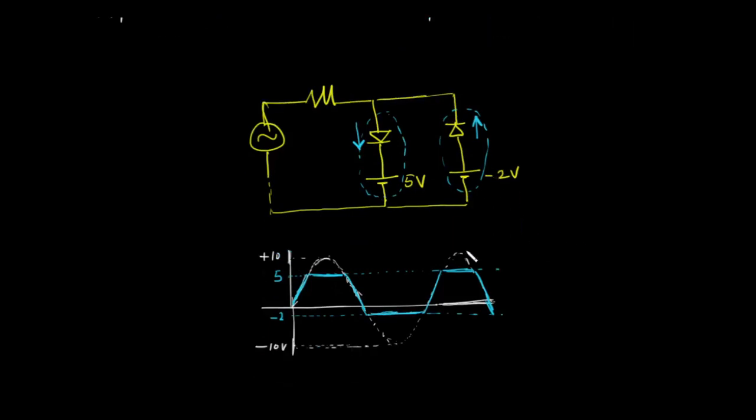In your exam you will be asked to, suppose, design a circuit. When we tell you to design a circuit, what you will have to do is basically draw the directions of the diodes properly, whether it will be a positive clipper or a negative clipper, and give the value of the voltage sources carefully. Suppose I give you a signal like this, and ask you to draw a circuit that will not allow anything above 3 volt to pass. So how will you draw that circuit?